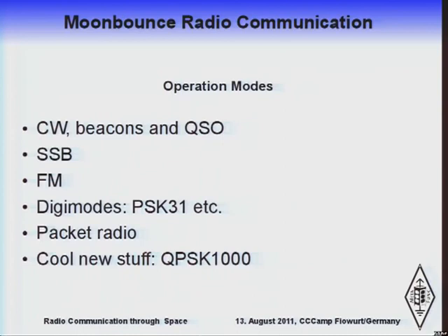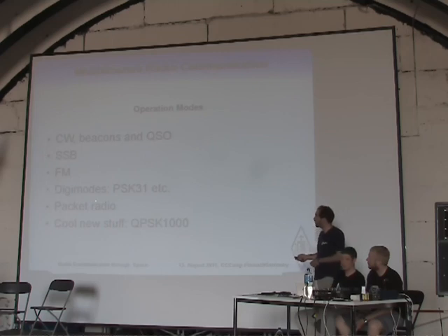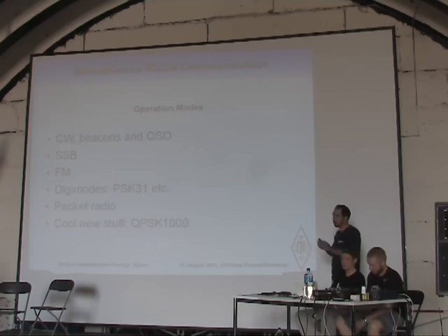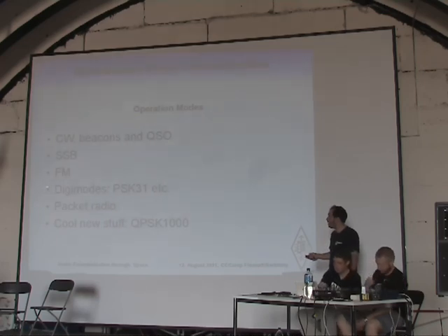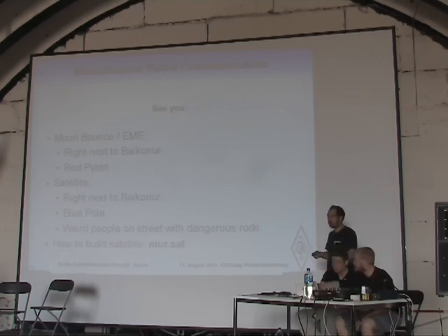That's the amateur radio term for a communication. You can do single sideband, that's an amplitude modulation scheme, which is more energy efficient. You can do frequency modulation, which is the same on your radio. You can do all kinds of digital modes, like phase shift keying, which is very narrowband, and all other kinds of digital modes. You can do packet radio, which is kind of like modem communication.